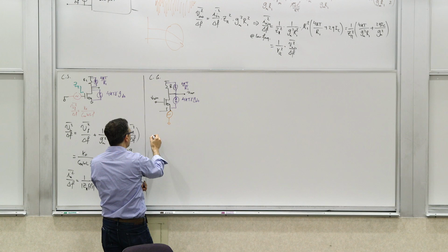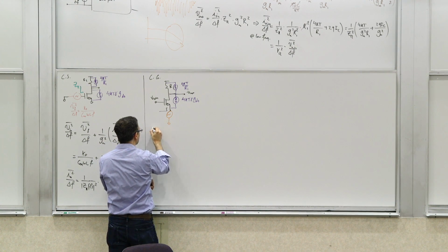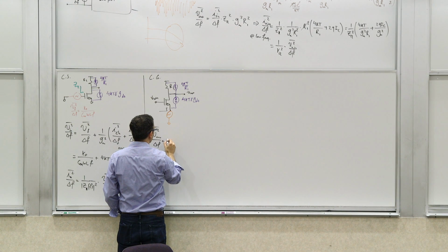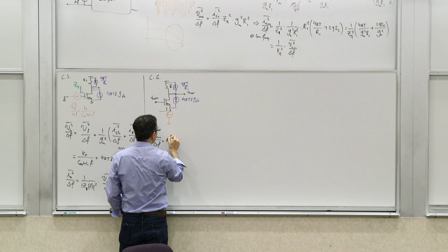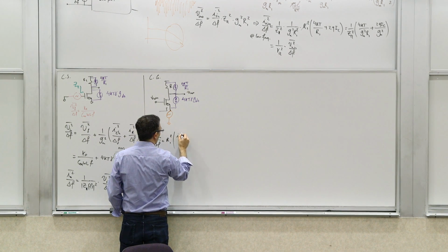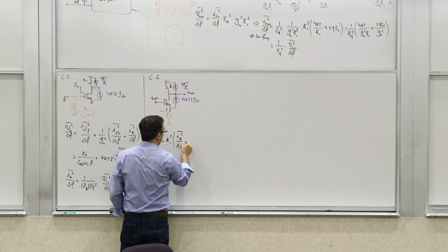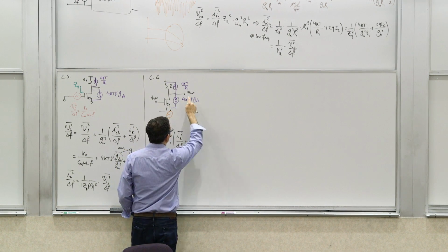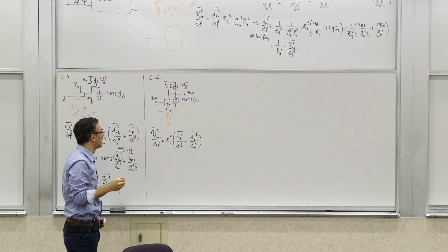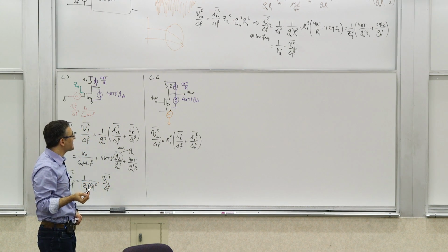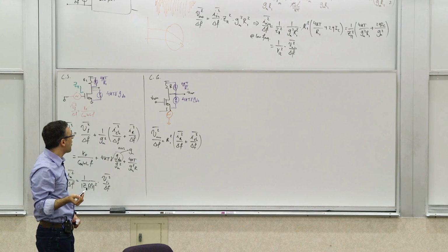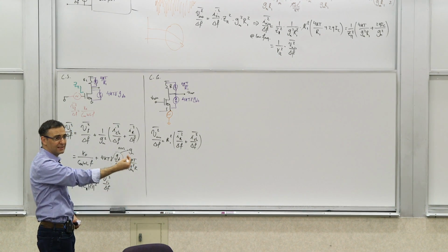So the total output noise, V out squared over delta F, is going to be R1 squared times I_R squared over delta F plus I channel squared over delta F, which are this and that. That's the power of the noise at the output. Now, I want to reflect it to the input.